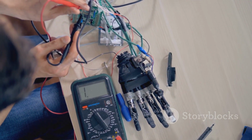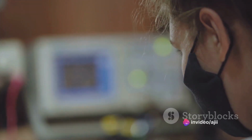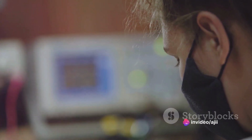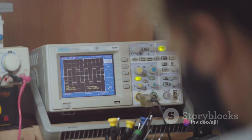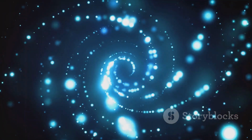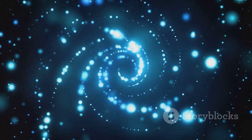But what if we reverse the voltage? When we swap the positive and negative ends of our power supply, the LED does not light up. That's the diode at work again. But this time, it's blocking the current. The diode is now in reverse bias, and the depletion zone within it acts as a barrier, preventing current from flowing in the opposite direction.